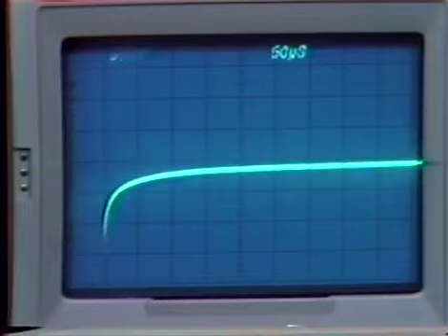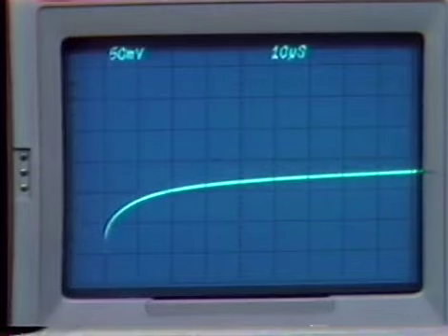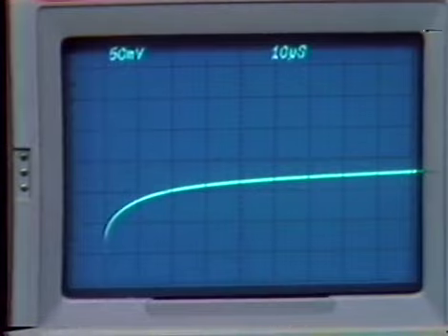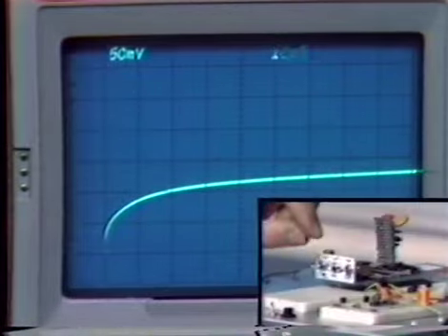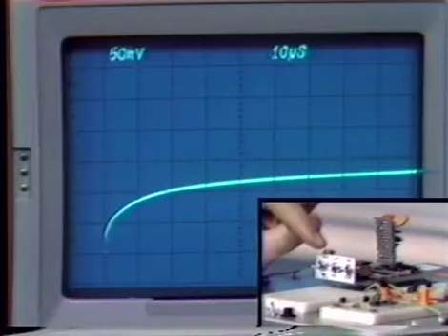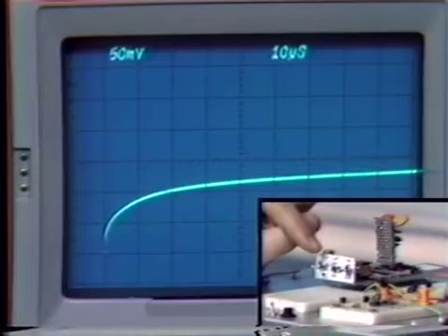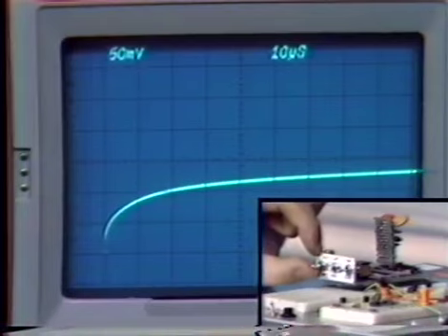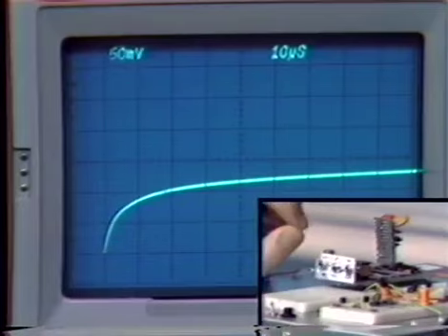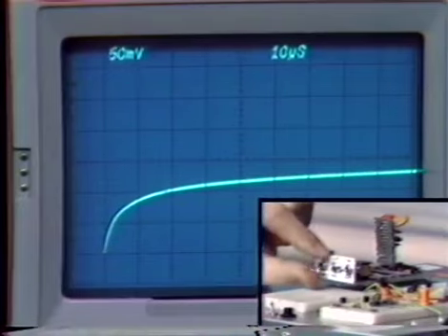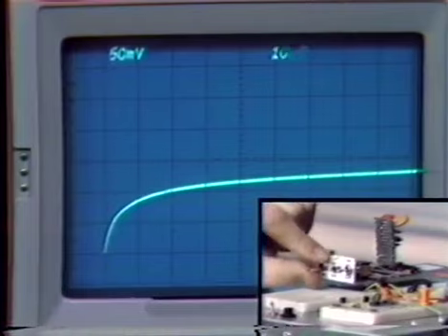that result when this sort of compensation is used. The good news is that we get very dramatically improved stability as we add capacitive loads or an additional pole in the loop transmission. Let me first of all add the pole at 1 megahertz. Again, not much happens. That is a sufficiently high frequency so that not much changes.